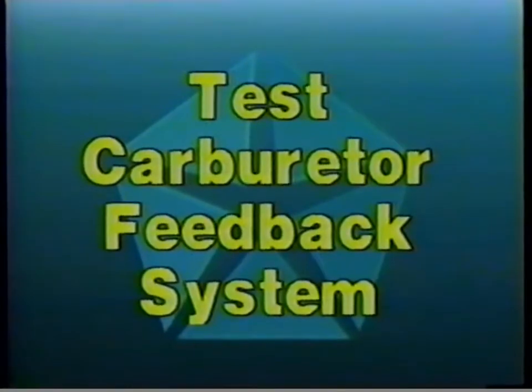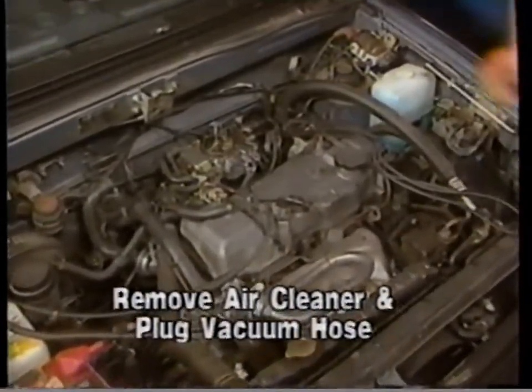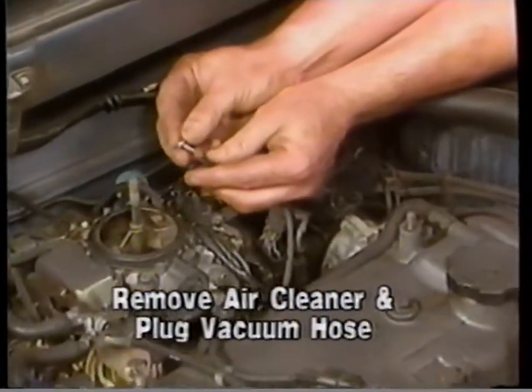The first part of this procedure involves testing the carburetor feedback system. For visual purposes, the hood has been removed for this procedure. To test the carburetor feedback system, first remove the air cleaner and plug the vacuum hose.